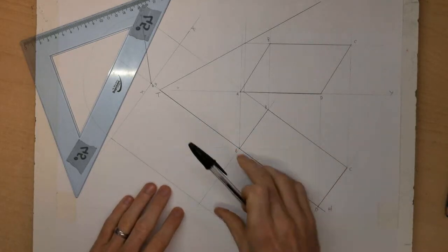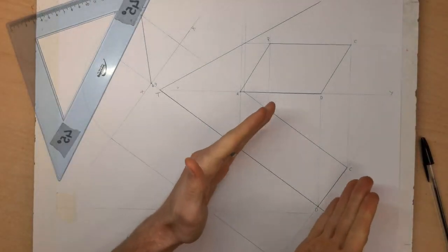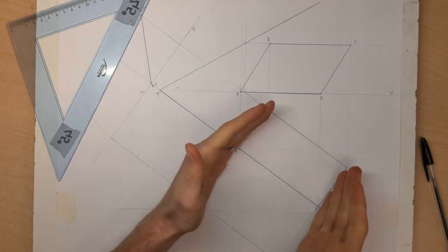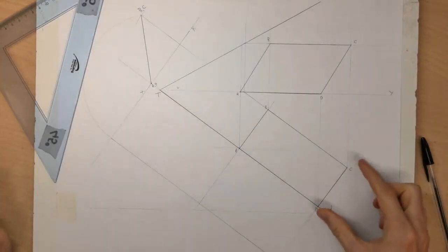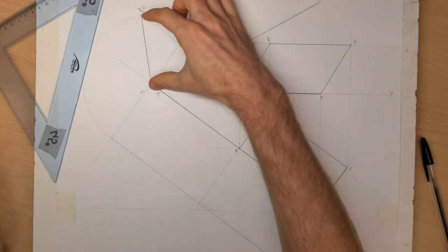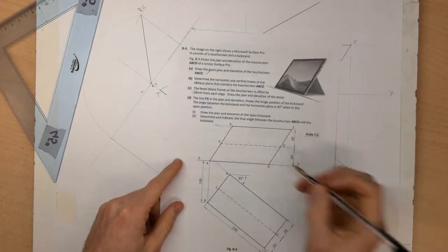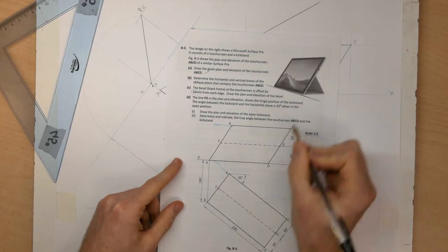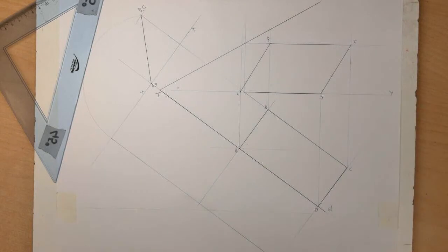So that rectangle there is the true shape of that surface, because we've got the true length here, if we're looking down on top of AD, so that's the true length. We found the true length in the auxiliary of line BC or AB and CD, found it there, so we now have the true length there. In the question, they said the bezel, so distance from there to there, or there to there, is 16 mil, so we divide that by 2, that's 8.